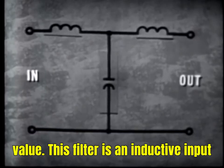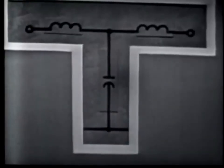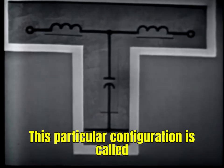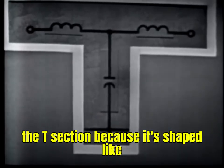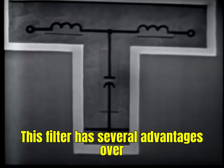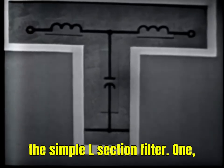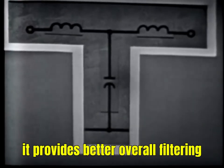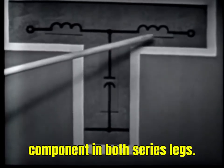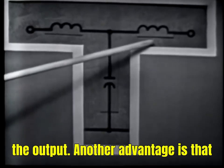This filter is an inductive input-output filter. This particular configuration is called the T section because it's shaped like the letter T. This filter has several advantages over the simple L section filter. One, it provides better overall filtering because there's a filter component in both series legs of the filter, both the input and the output.